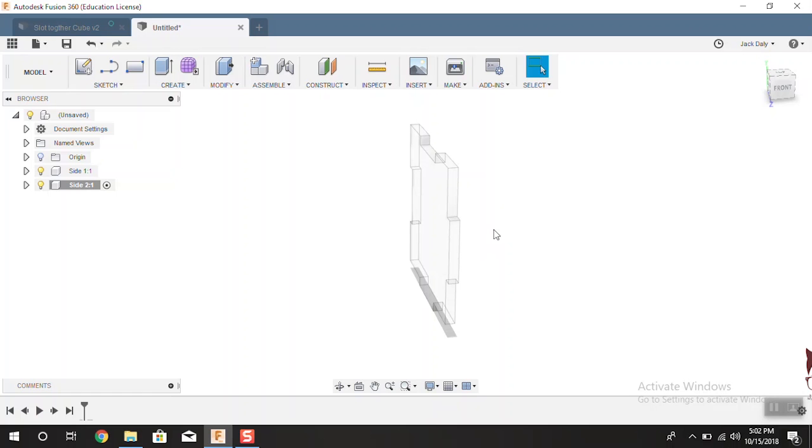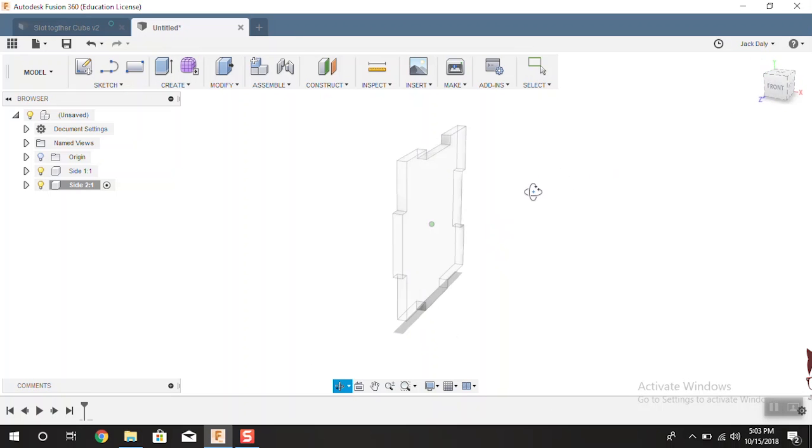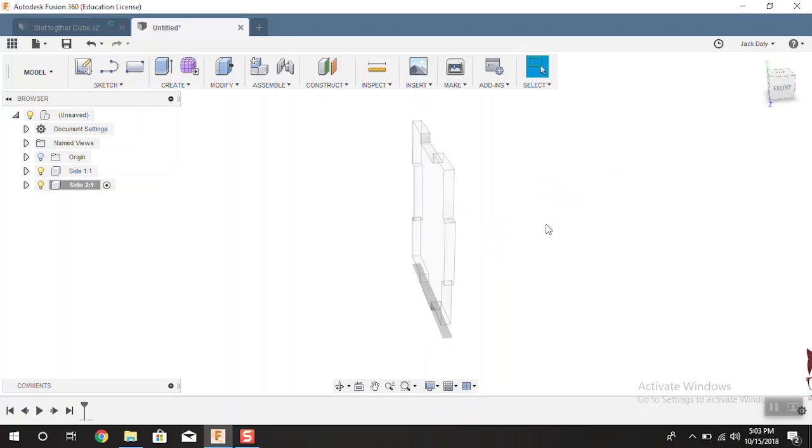So bottom-up design is where you would make each individual panel in separate files and then all put them into another separate file where you then assemble it. But with this one we can obviously do it, and it's much easier. So then you want to click on front, and you want to click create sketch, making sure this is active.